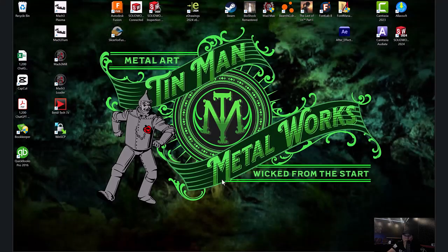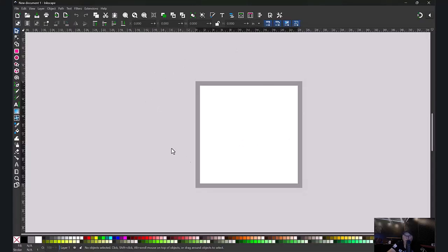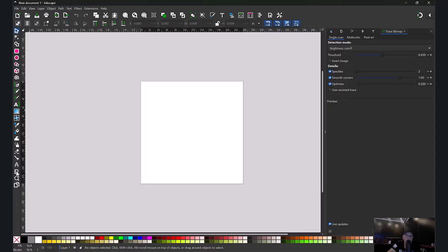So now I'm going to close out of this window. I'm going to open Inkscape back up. That welcome window didn't pop up again, and my icons are changed to a larger size. My color palette's changed the way I did it, and my artboard is 24 inch by 24 inch. And that is how you set the defaults in Inkscape.